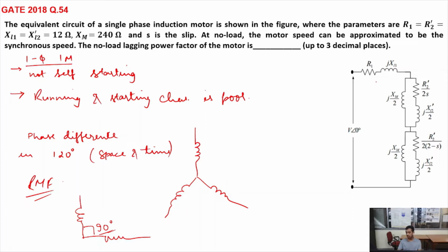Here in induction motor, this is the forward EMF and this is the backward EMF. Now there is only one phase of winding, so the winding can be written as Fm cos theta cos omega t. So this is the time, this is the space angle, right? Now, can we break it into certain two-phase type of thing? Certainly we can. We will break it.